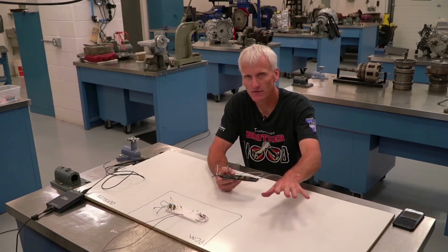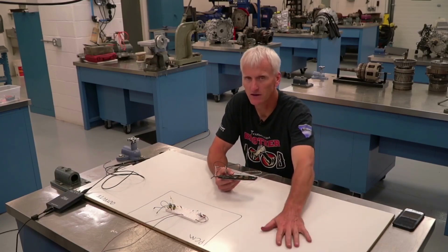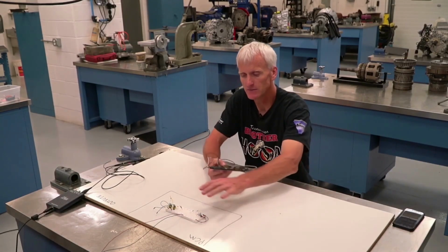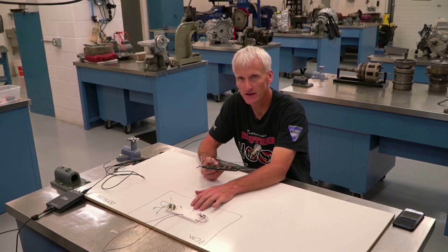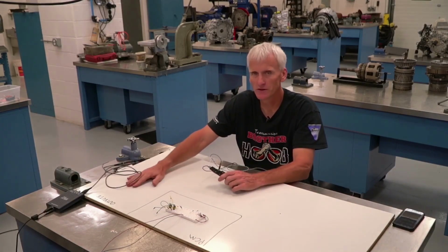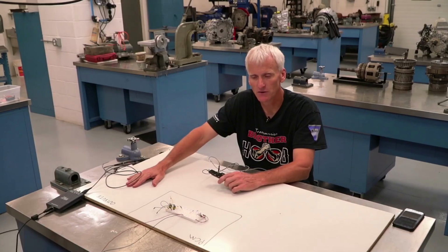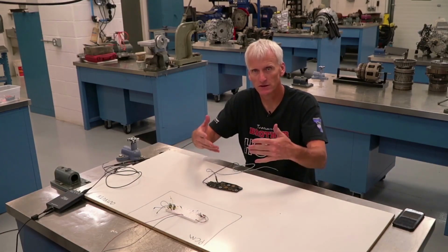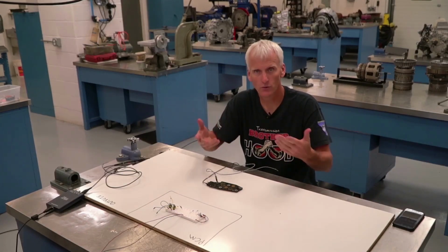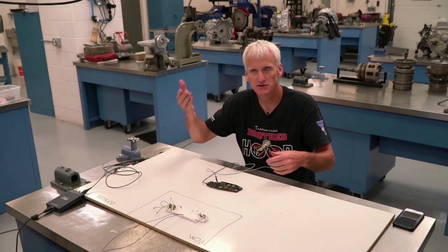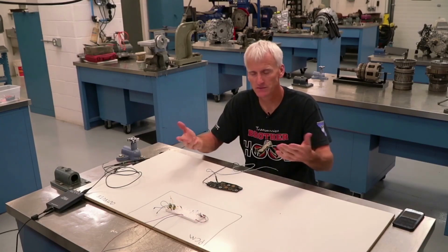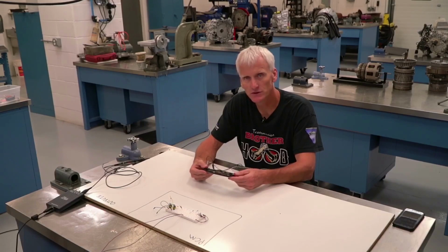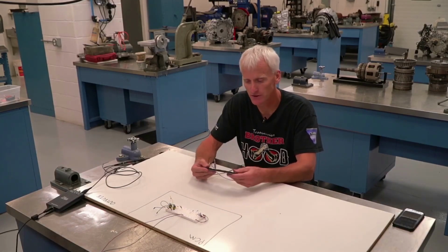Just kind of get into this right off the bat. Your computer is going to look at all the input devices, things like switches and sensors, and it's going to make a decision based off of that information. And then it's going to control the outputs based off of that. So it's kind of like in a normal computer where you got a keyboard and a mouse. Those are inputs. And then the computer interprets what you're wanting to do and then it controls the screen or a printer or does some calculation for you, and that's an output. There's no difference really in a transmission operation.